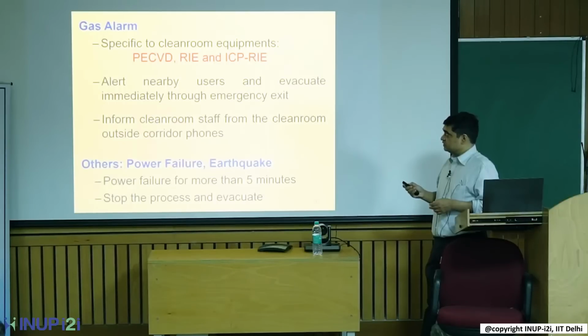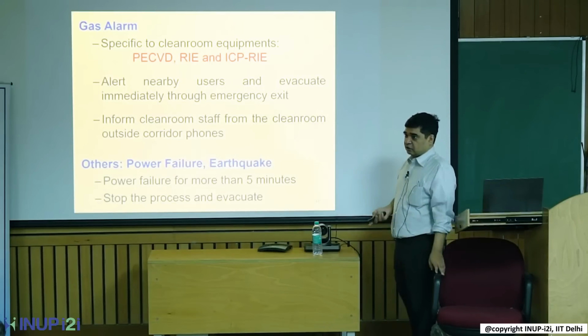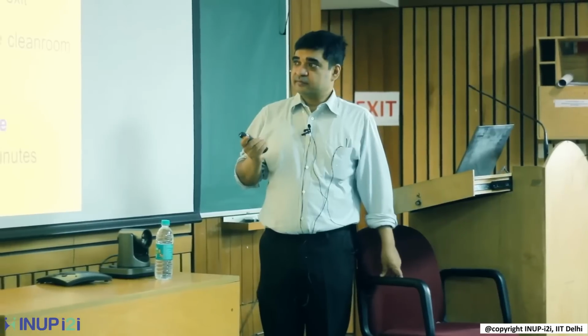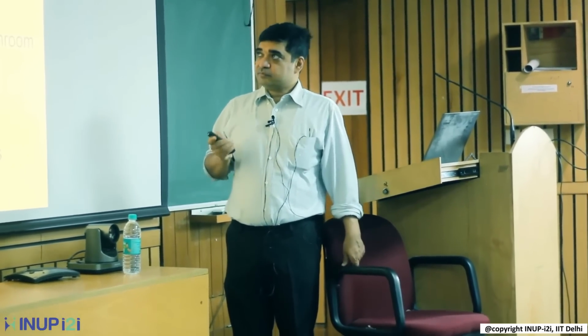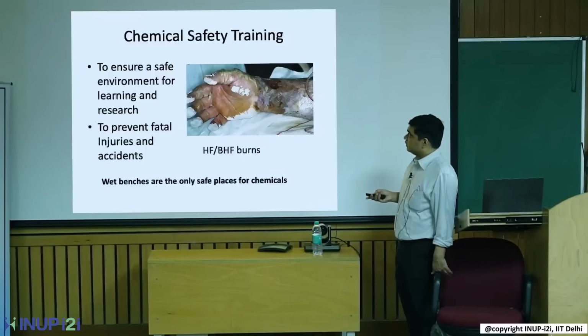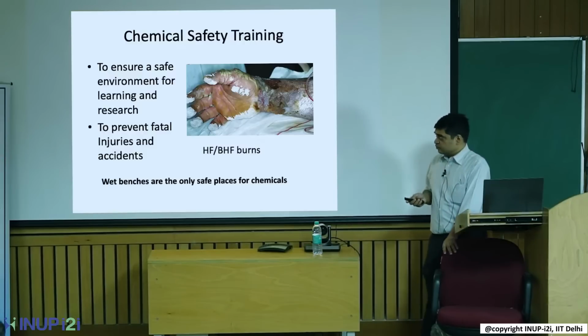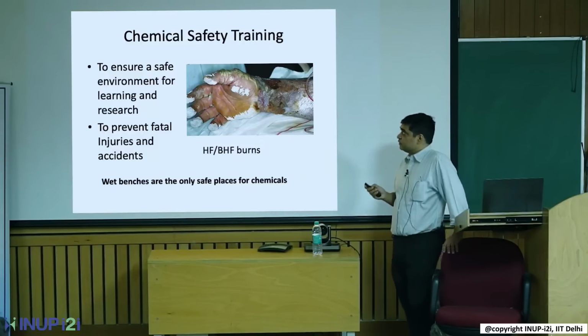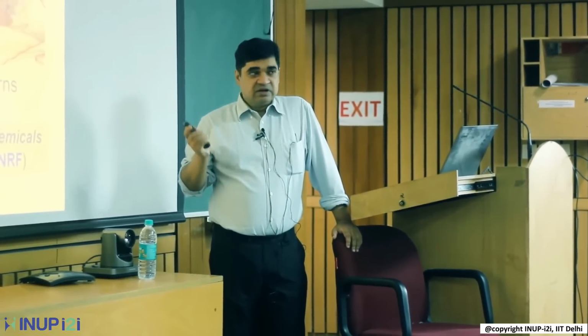I think not so much here. This is more of a concern because it has silane, arsine, phosphine. These are all hazardous gases. So if they leak, there's a fire alarm here, gas alarm here. So that's the emergency protocol. Coming to safety, there have been a couple of accidents worldwide in labs, and usually it's the